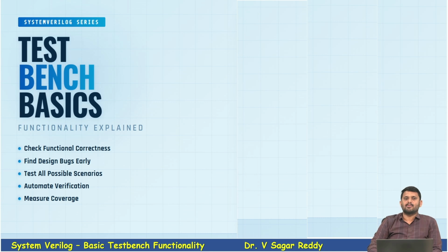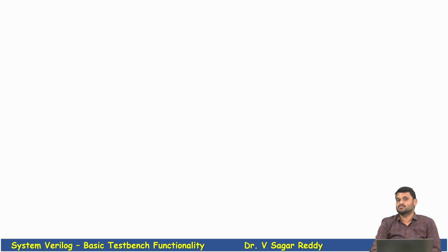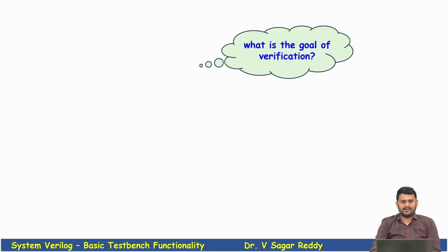Before we start learning about SystemVerilog Testbench, let's first understand an important question. What is the goal of verification? Why do we spend so much time and effort verifying designs that are already written and seem to be working? If you answered finding bugs, you're only partially correct. The main goal of verification is to make sure that the design behaves exactly as intended, under all possible conditions, before it's fabricated into hardware.